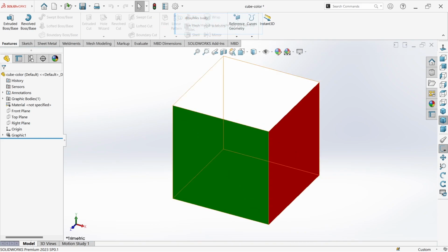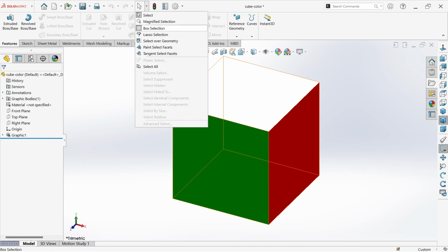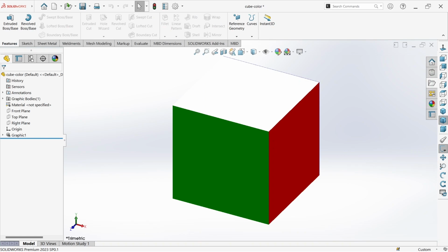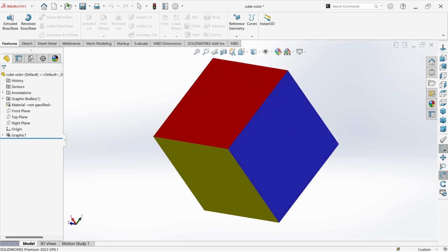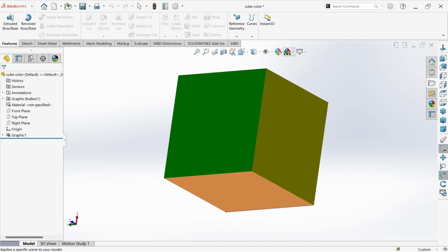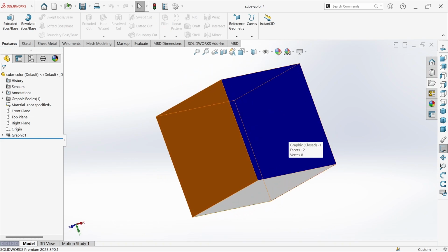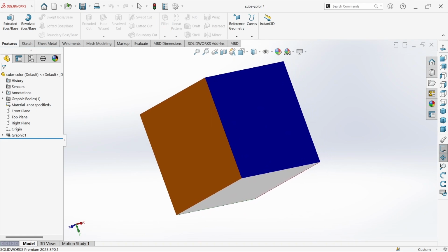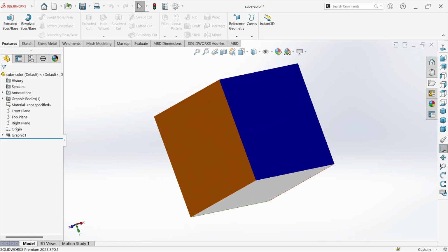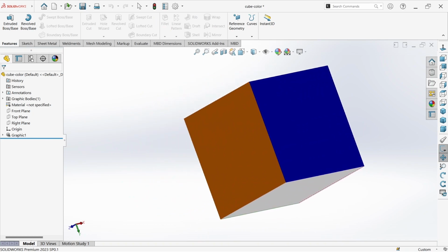Alright, so in here, how do you navigate? Press the middle mouse button and you can see that something changes in the top bar. Previously it is like a mouse, but it changes as soon as I hold the middle mouse button. By holding the middle mouse button and dragging, you will be in the rotation mode. Let's say I want to pan it. In that case, press control and the middle mouse button. That is how you pan across the 3D model.